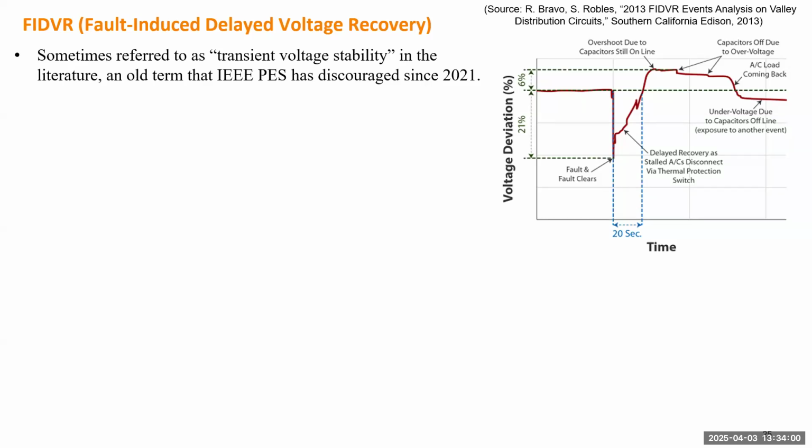So this is one story showing the lack of a dynamic controller like a synchronous condenser, SVC, such type of device. If you only utilize capacitors, reactors, to try to support voltage or limit voltage, you may not be fast enough. Okay, the system will have either under voltage or over voltage. What happened is that when the voltage is recovered, the capacitor still stays on the line.